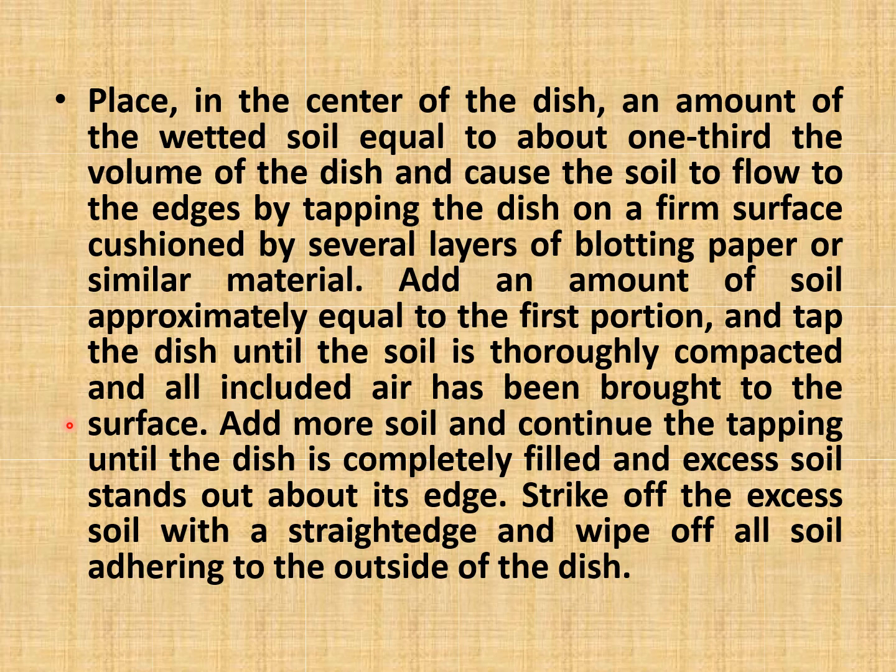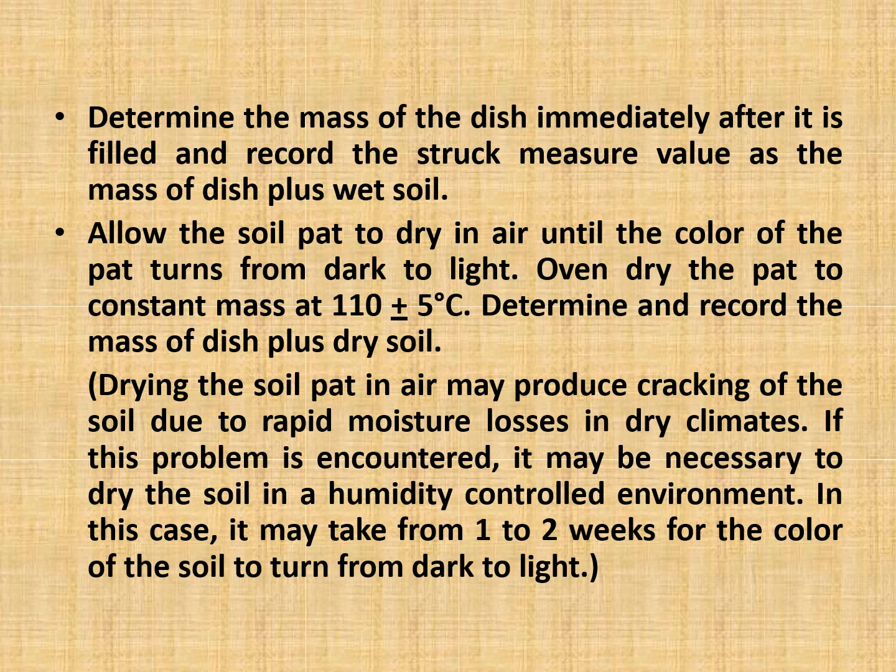Add more soil and continue the tapping until the dish is completely filled and excess soil stands out about its edge. Strike off the excess soil with a straight edge and wipe off all soil adhering to the outside of the dish. Determine the mass of the dish immediately after it is filled and record the value as the mass of dish plus wet soil.